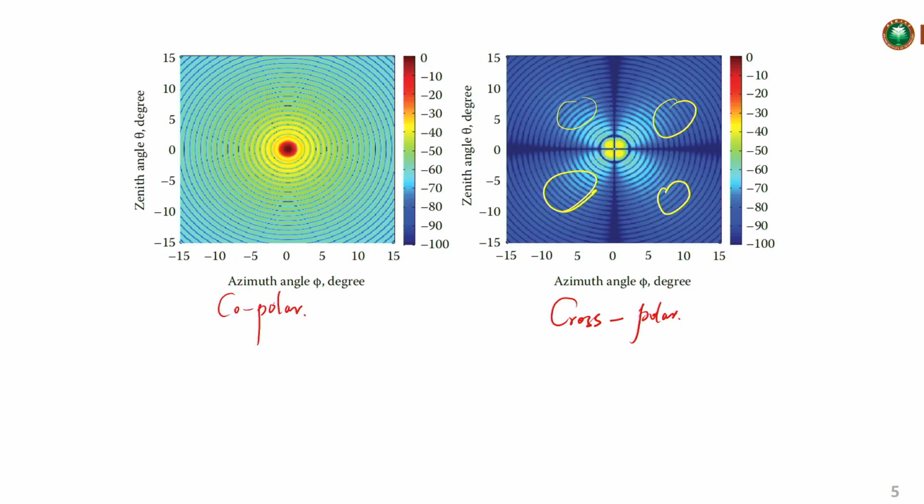So this means if we use the polarimetric radar systems, for this kind of radar, the WSR radar systems, it can lead to a polarization isolation of around 40 dB. So this is very high, all right? Especially when we want to obtain the details about the hydrometeors, we need a very high polarization purity. So this configuration is very useful and mostly employed.